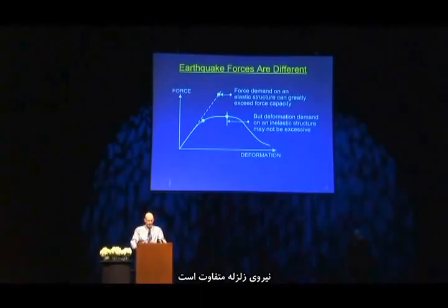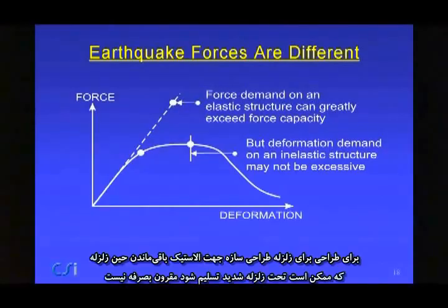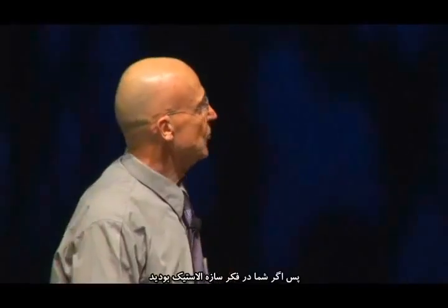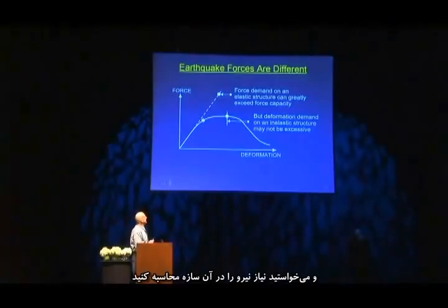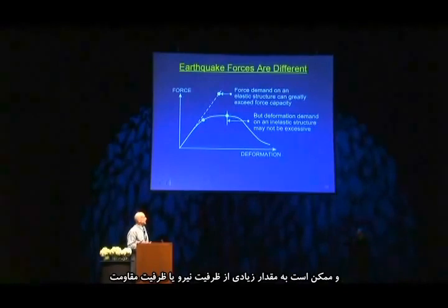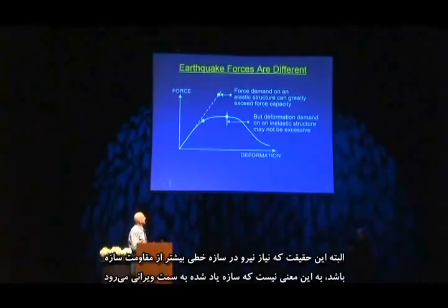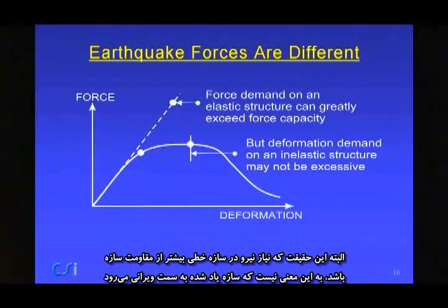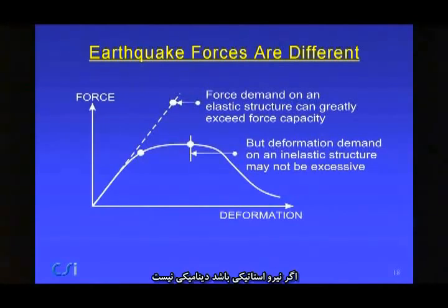Now, earthquake forces are different. The conventional wisdom says it's not economical to design a structure to remain elastic during an earthquake. It will yield under a strong earthquake. So if you were to think of an elastic structure and you were to calculate the force demand on that elastic structure, that could substantially exceed the force capacity or the strength capacity of the structure or some or even possibly all of the components. However, the fact that the force demand on a linear structure exceeds the strength of the structure doesn't mean to say the structure is going to collapse. It would if the load were static, but it's dynamic, and so the structure does not necessarily collapse.